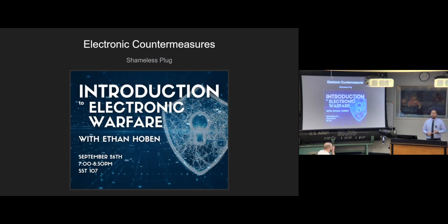Most systems start implementing things called chirps. Chirps are insane because it's a signal. If you've ever heard a sound that goes woo, that's a chirp. A chirp is a continuous signal with a massive amount of frequencies in it. So if I blast you with a chirp pulse, I hit all those frequencies at once, or at least very quickly after one another, which means all those narrowband solutions are invalidated. They're not that useful anymore.